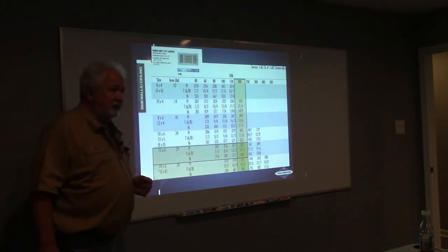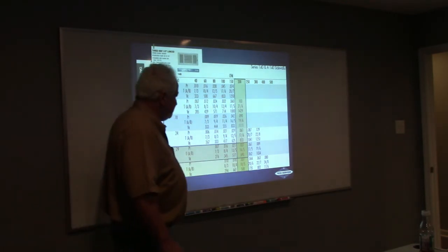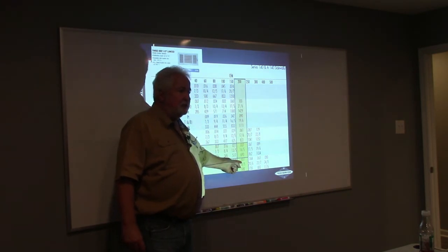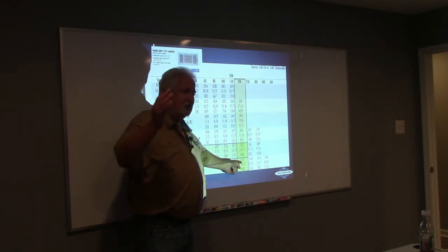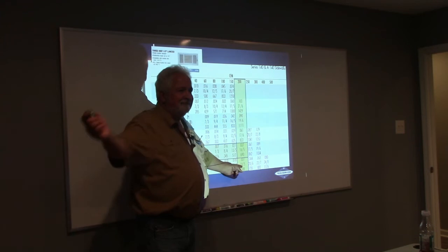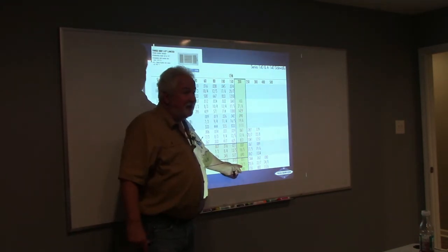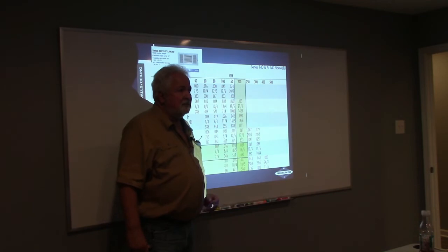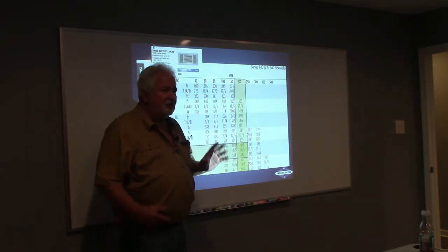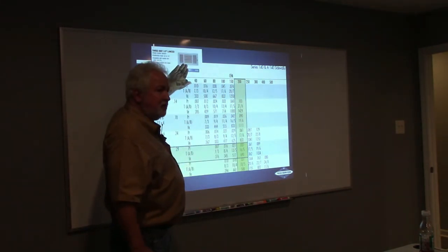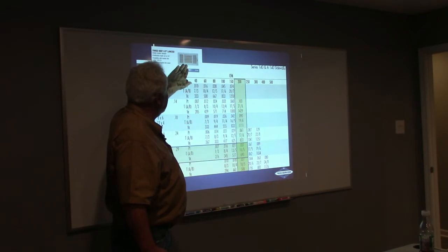So let's try a 14 by 6. Let's see what that looks like. 0.027, how's that working out? We wanted somewhere between 0.02 and 0.03, so that would be a great number for us to be working with. It's going to throw at 18 feet. That's almost 20 feet, right? We've really got our throw too far on this one. What about this 588? It's a little high. Maybe that doesn't work as well as we want, so maybe this particular grill is not the one we want. Let's try that other grill.